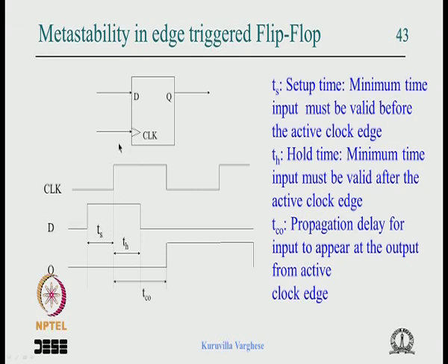Of course normally in the clock path there will be inverters to choose the correct polarity and to choose the opposite edge for the slave and all that. So normally there will be 2 inverters. That inverter skew has to be removed from the setup, and the hold time is that inverter delay itself, because even after the clock going high it takes that inverter delay for the master to cut off. During that time the data should not change.